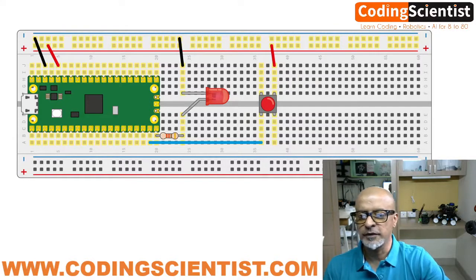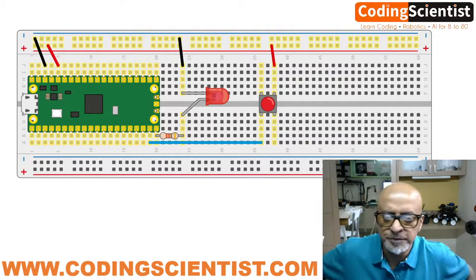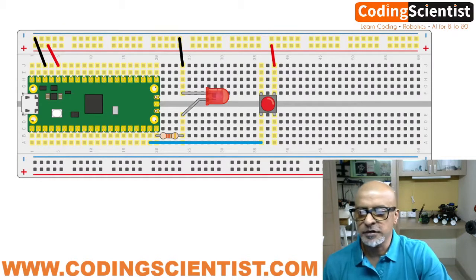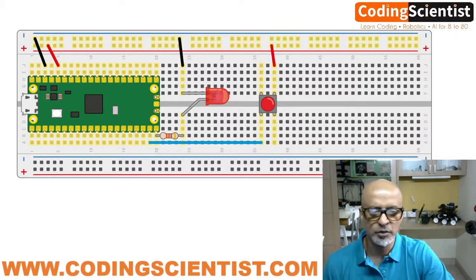Let me just double verify again. Basically we are importing machine, from machine import Pin, and then import time, and then LED equals Pin. We are assigning it to pin number 15, and we are sending the signal, Pin.OUT. All right, and then the button equals Pin, again from pin number 14. We are taking the input, Pin.IN, and the input is basically the pull down from the push button switch. All right, that is Pin.PULL_DOWN.